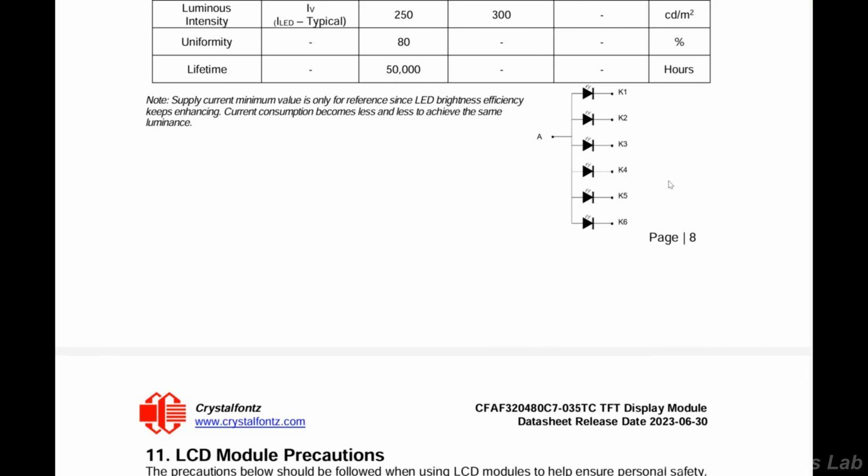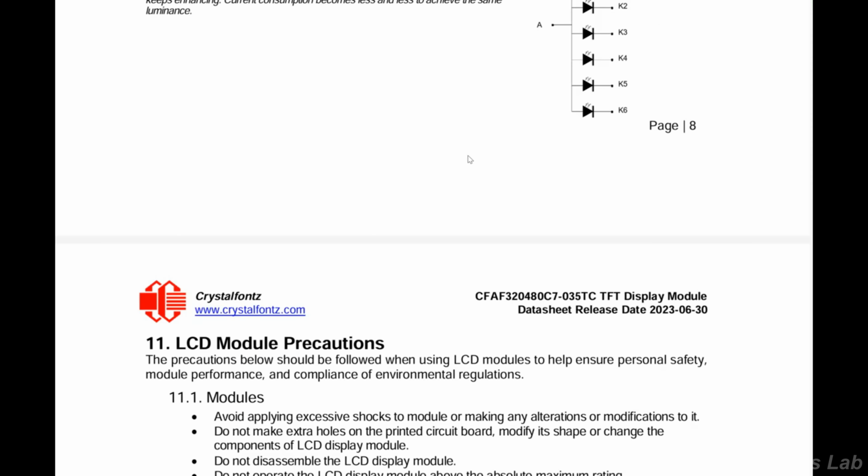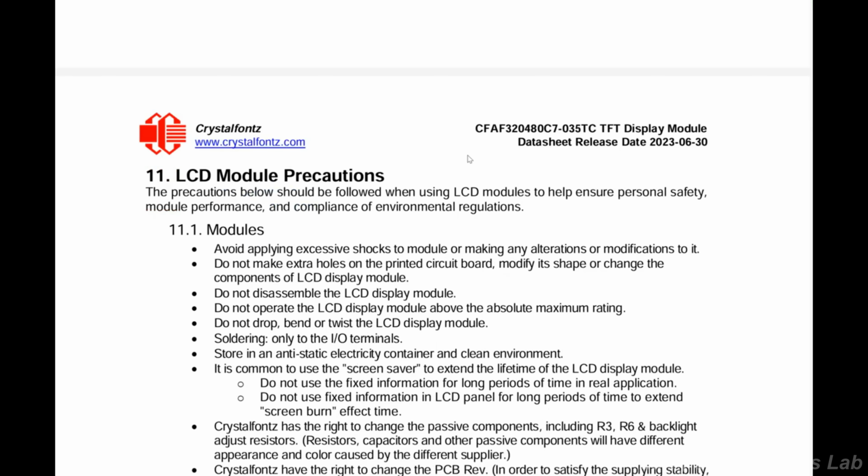So some people, if you want to get picky and you want a really smooth, nice backlight, then you use a constant current chip when you power the backlight so that each one gets precise amounts of current. But I just power it with a PWM, and then you can control all of them equally. I don't get too fancy with that, and it seems to work really well.